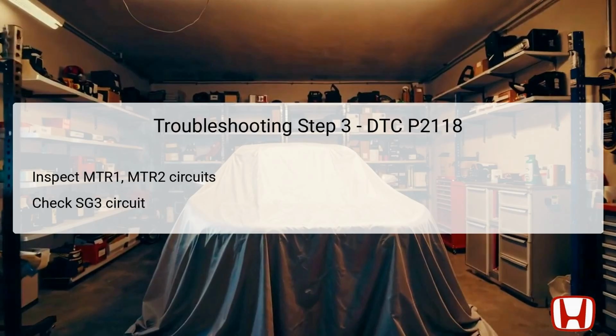After setting up, check the SG3 open wire for resistance, ensuring it reads below 1 ohm for a healthy circuit. Verify MTR1 and MTR2 for shorts. These should exceed 1 mega-ohm. Anomalies in these readings suggest wiring issues, leading back to the PCM or throttle actuator malfunctions.